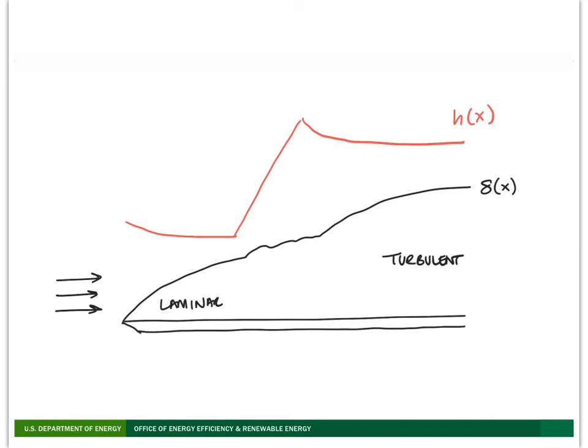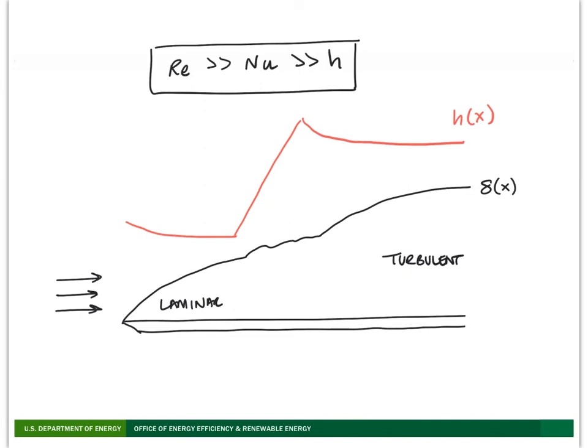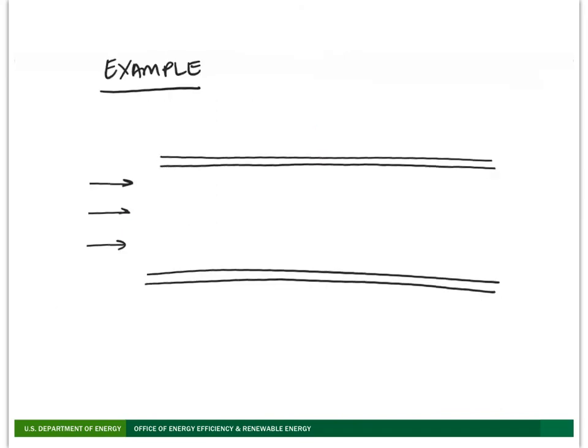When we go to determine all of these things, if we were going to actually do this calculation, we would start by first calculating the Reynolds number. We'd use the Reynolds number with a correlation to calculate the Nusselt number. And then we'd use that to calculate the heat transfer coefficient based on the definition of Nusselt. So this is sort of a shortcut. When you think about these calculations, oftentimes we go Reynolds to Nusselt to h. And then h, of course, characterizes for us the flow and what's actually happening from a heat transfer standpoint. And that allows us to put all of the pieces that we need together. So let's go back to the example we had with the duct for just a minute.